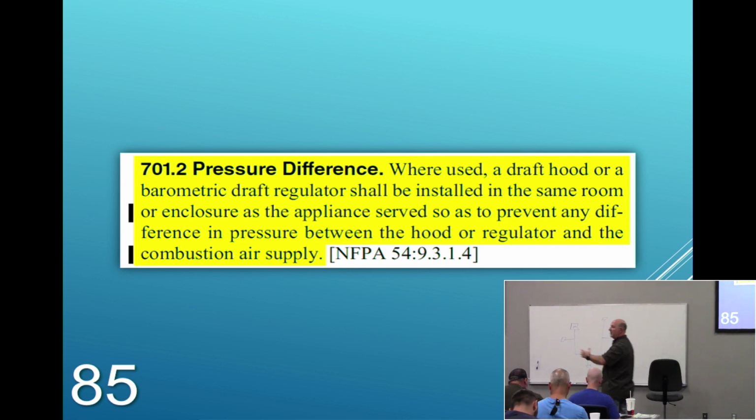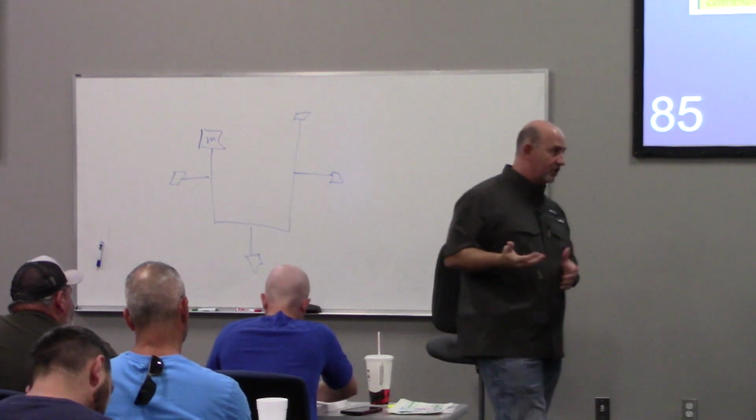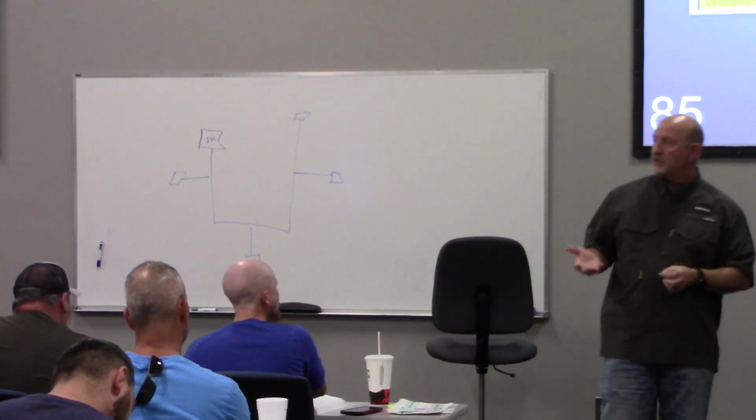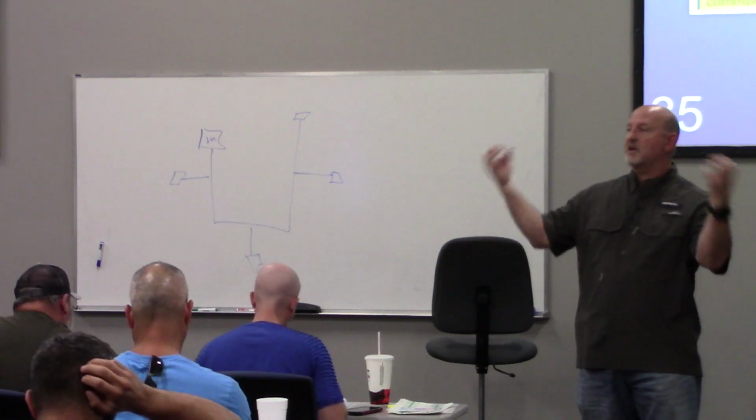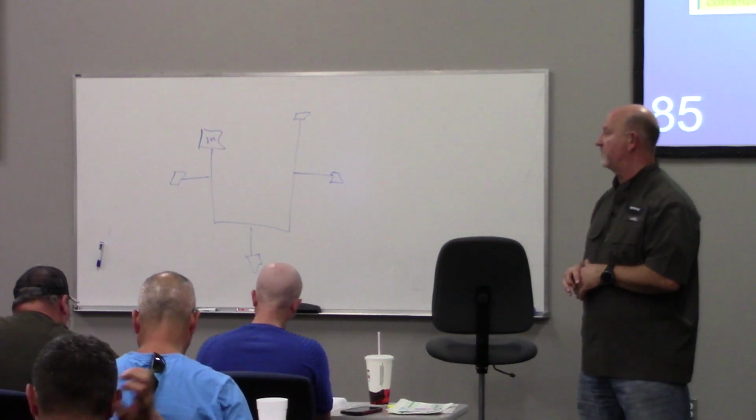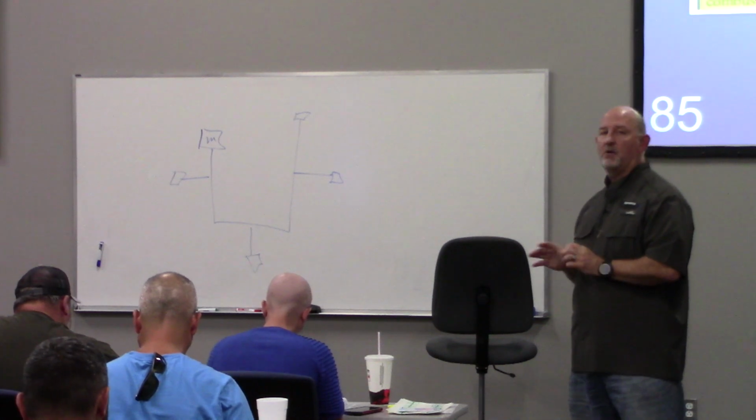Indoor. So look at me. That's this room right here. If I was writing the code, I would change that word indoor. I would change it to in room, just to be more specific. So this guy is going to tell me how big my room needs to be to get my combustion air from inside the room specifically. Okay? Now, we'll talk more about that, but before we do, let's talk about who is 701.5 real quick.